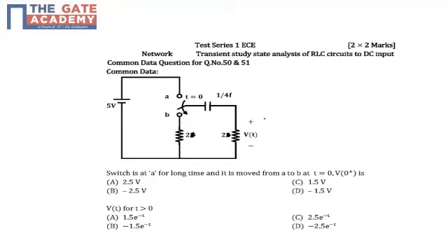So we know that the circuit is such that the knob T is connected to the point A, and the circuit is in steady state. At t is equal to 0, we have changed the knob from position A to position B. Before this change has occurred, my circuit is in steady state, and we know that the capacitor opposes the sudden change of voltage.